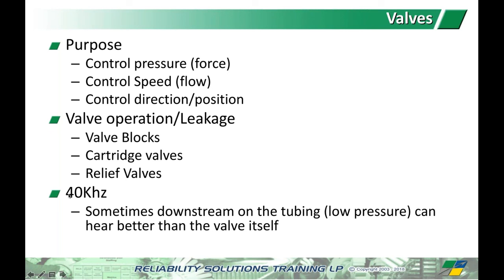Typically my setups here, I'm going to use the contact probe, and I know that for valves you're supposed to use, I think, 30 kilohertz or different things. I've had really good luck just sticking with the standard 40 kilohertz and listening to valves. When you're on a directional control valve, you need to see what the schematic or the section of the valve looks like, and of course you want to try to physically get as close to the valve seat as you can, because obviously that's the bit that's going to be leaking.